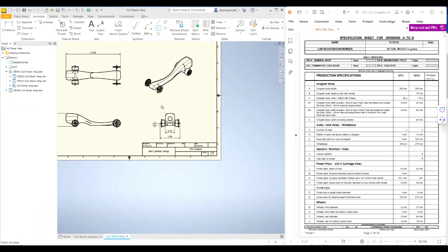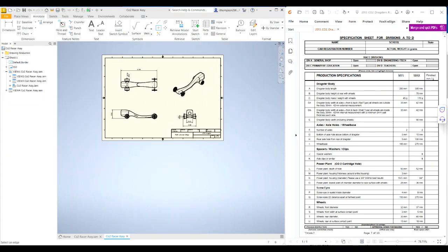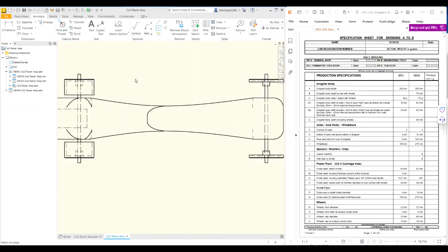And in fact, there's another kind of center line that we could use, which is actually pretty useful. Let me just zoom in correctly. See, these axles here could have a center line as well. The way we would do that is click here, center line bisector, and then choose that line and that line there.